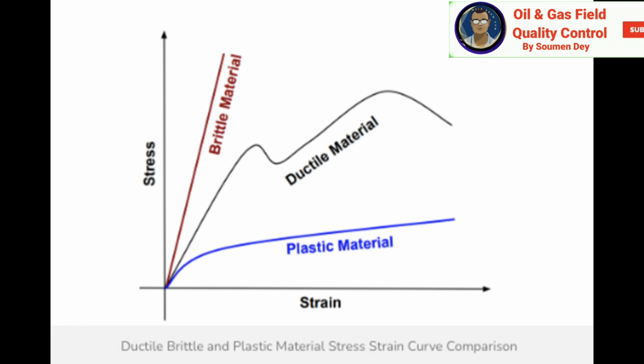In the curve, you can see the plastic material. It is taking permanent deformation at very low stress. Brittle material breaks with small elastic deformation and without plastic deformation due to the external force. In other words, a brittle material's elastic limit, yield strength, ultimate tensile strength and breaking strength are all equal. Brittle materials absorb relatively little energy before fracture. For example, brittle materials such as pencils or glass break suddenly with a snapping sound and small deformation. Ceramic, wood, glass, graphite and cast iron are brittle materials.